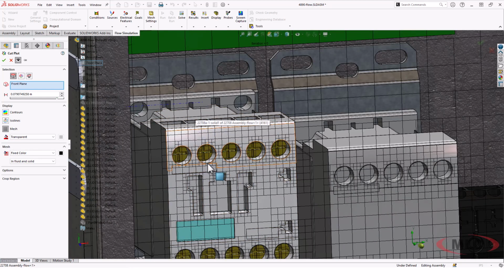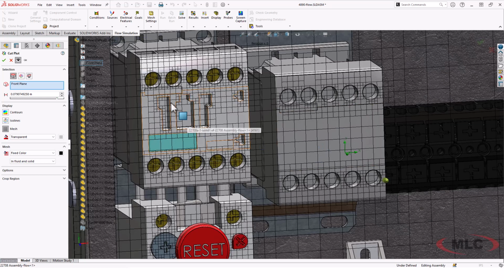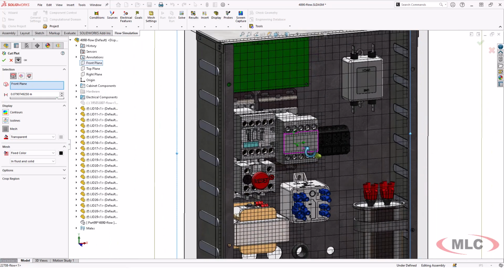So it went to the full level 5 all around all these little features. So one solution to lots of refined edges is to clean it up like I did on this one where it removed all those slots. But that's just not always feasible. What I want to do is tell the mesher to just ignore boring little areas like this that don't mean anything. All right. So that's a problem I want to fix by reducing the complexity there.